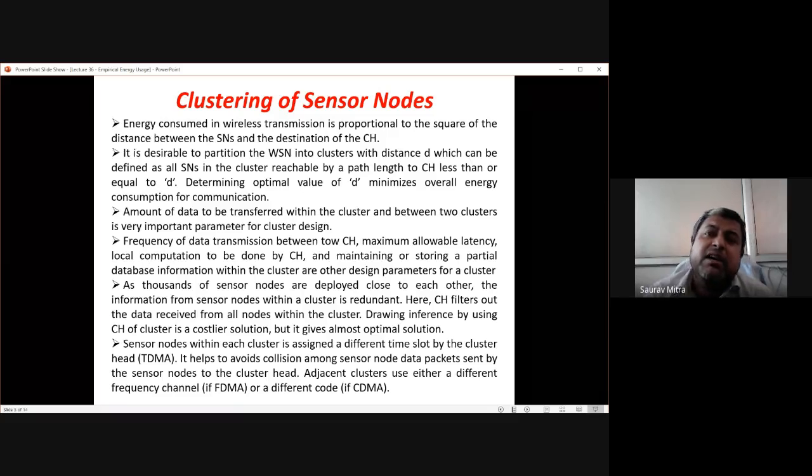So generally, if there is a cluster head and 4 different sensor nodes sensing temperature in the whole area, they directly dump all those 4 sets of data into the cluster head. Then the cluster head, depending on the position of each sensor node, mixes the data and prepares an overall temperature map of the whole cluster for which it is deployed.